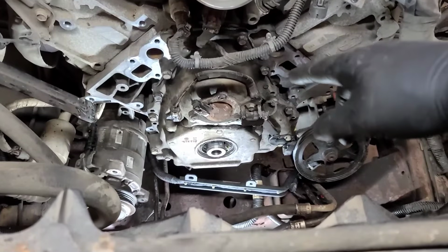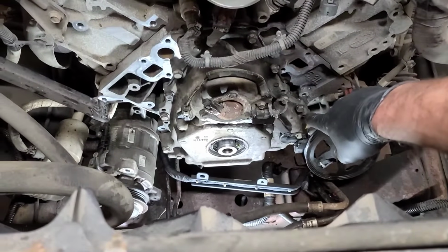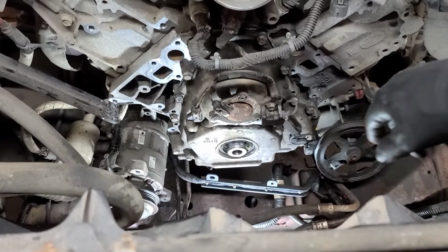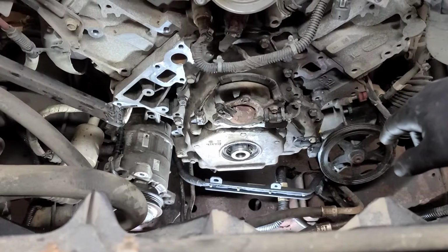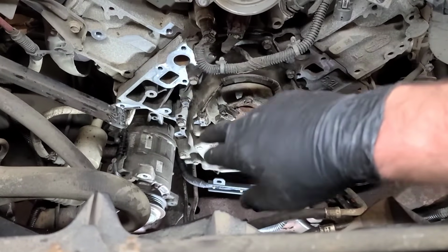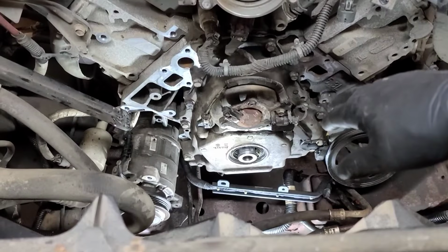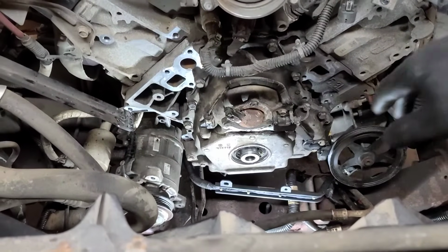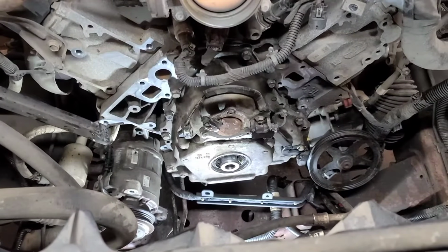So the bolts on the front cover are 18 foot-pounds. Start over here, go 1, 2, 3, 4, 5, 6, 7, 8, 9, 10, you know, starting at the center and working toward the ends. 18 foot-pounds. A bead of RTV sealant on the cover is easier than putting it on the block. Just be careful not to touch anything on the way in, smudge it. Make sure the surfaces are spotlessly clean. Wipe them off with a clean rag and brake cleaner.